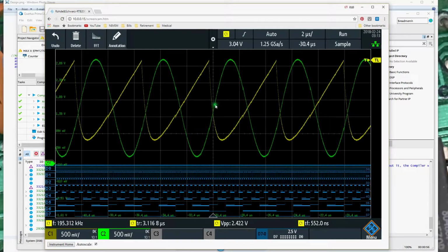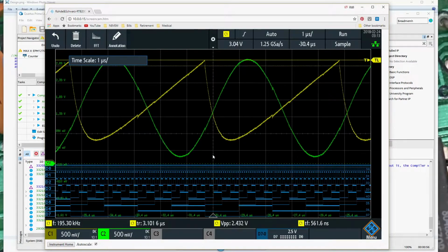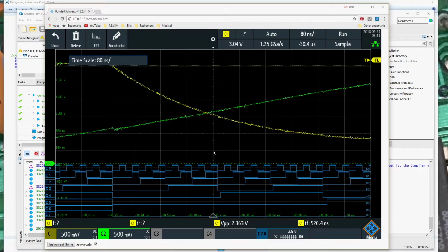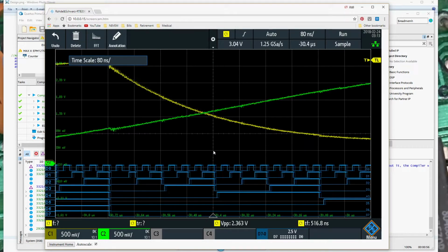So remember here at about the center, it's 80 hex, 83 hex, 85 hex. With the smaller transitions here, we're getting essentially better signal fidelity because we don't have these really large changes in output from about 3.3 volts to 0 on a single clock. We can zoom in here, and of course there's a fair amount of noise.